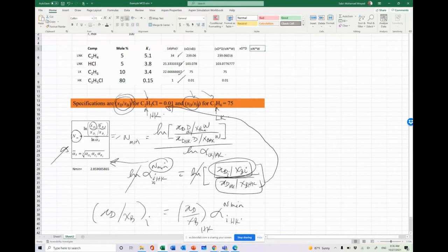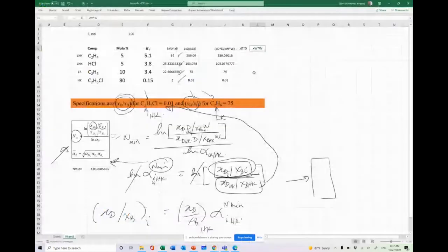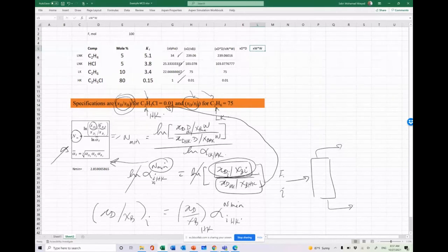Okay, so let's see from the material balance point of view. If you go back to your column here, and hopefully you follow me, guys, you have three components, or any component. Let's call that component i. And this i is basically, let's call it Fi, the flow rate of component i in the feed. You have the flow rate of component i in D and the flow rate of component i in W. So first of all, Fi is basically Di plus Wi.